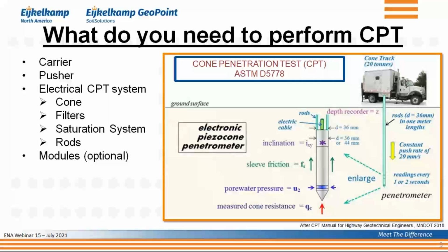I would then get a 15 centimeter square cone, subtraction type cone, that I would use for the rough, stiff soil layers that I have to go through, and I would get a 10 centimeter square compression type cone, so I can do my measurements in sensitive soils. I have then a backup, and then I probably have the widest range, and still use then my 36 millimeter rods.